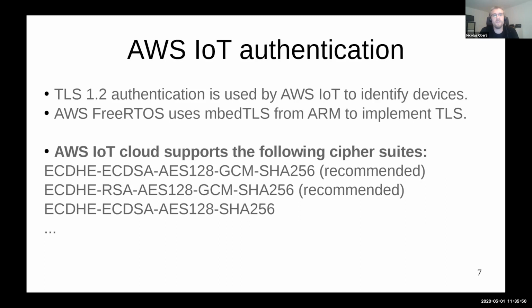So Amazon provides a lot of boilerplate code that you can use. They have a basic image which uses FreeRTOS, and this image uses mbedTLS. And if you get this basic example, you are able to connect to the cloud and make a LED blink on your device. So we got some interest in that.